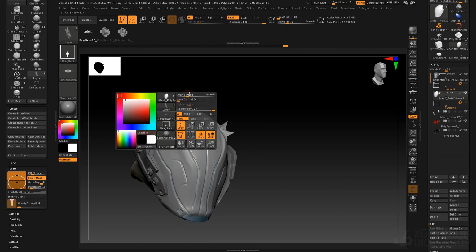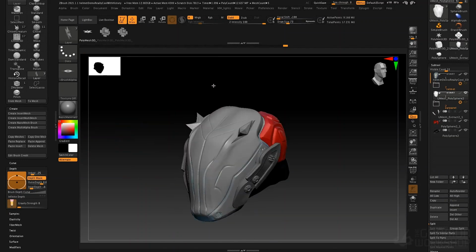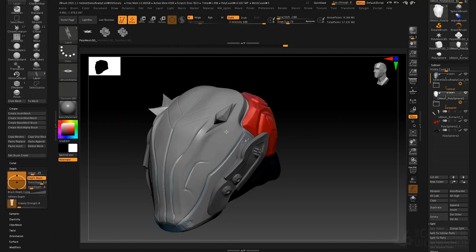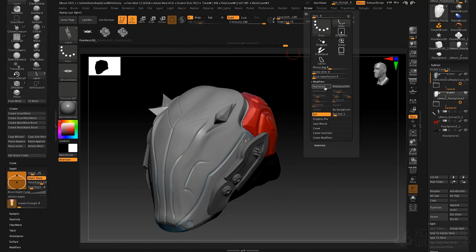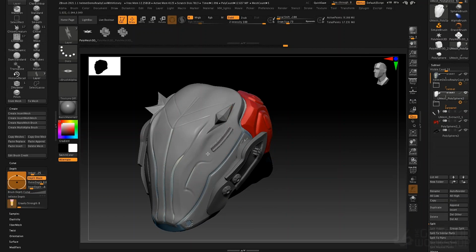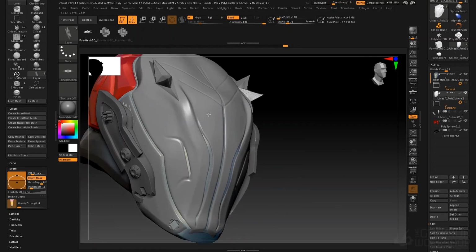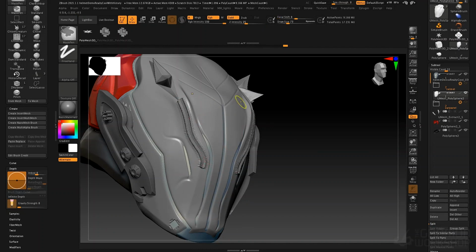So it's one thing to do these with just a single drag rectangle. What if we wanted them to follow a path? So what I would do then is change to my dot stroke, click drag, and it's going to draw these alphas out along a stroke. Now that's not the default behavior. I'm going to go to the stroke menu and turn off roll. So this is what you will typically get as your default behavior, and this may well be something that you want. So if we come over here, zoom in a little bit, draw our stroke, that type of shape may very well be something that you'd like to see on your surface.